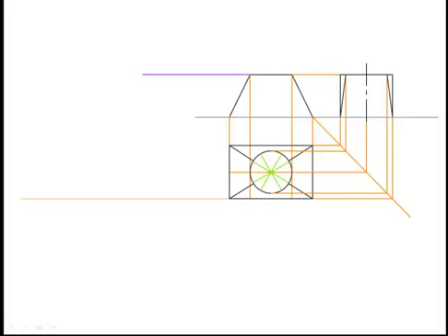The purple line in elevation helps create the true heights from plan by rotating our sectional points from plan up to elevation, as shown by the purple line, which is rotated from plan and is brought vertically up to the elevation till it meets the purple height line in the elevation.